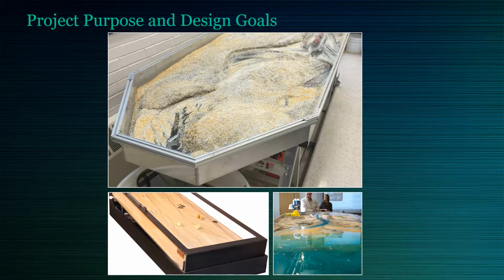If you're not familiar with them, a stream table has a reservoir of water underneath the sandbox-style thing you can see in the pictures here. The water is pumped up with a water pump, and then the water flows down through the media and simulates and models rivers. The way that people use these are for sediment transport, geomorphology, dam simulations, fish passage, hydraulic structures, hydrology such as groundwater flow, flooding events, and also for soil science like soil conservation.